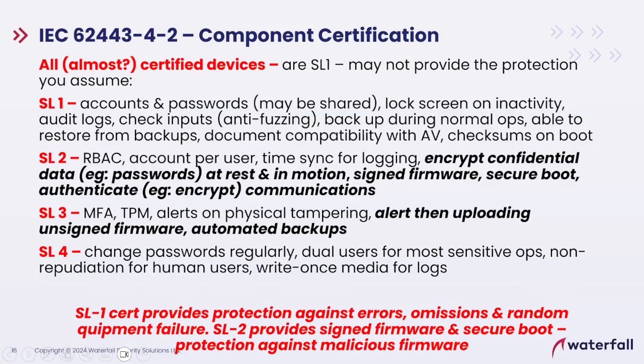I see a lot of people in industry increasingly are specifying certified devices. They only want 62443 certified devices in their OT networks. 4-2 is the standard that certifies. Here's the thing. As far as I know, almost all, possibly 100% of these certified devices are certified to SL1.